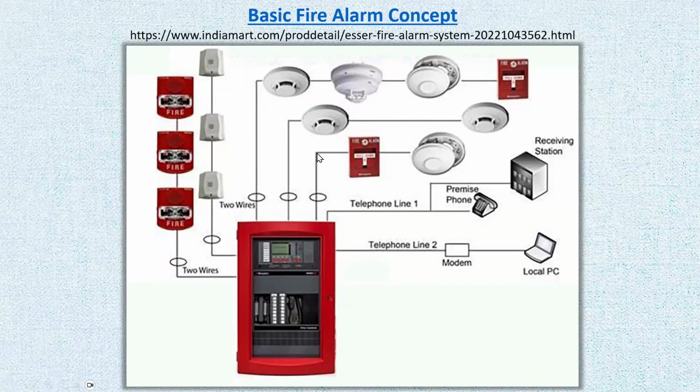Now, some of the devices can be triggered by pressing a button, like those heat detectors. They do have buttons to be pressed, like a test button. If there are smoke detectors, they can blow some smoke on it, and there's something that's called smoke in a can. It's just like a deodorant type of can. But it's called smoke in a can, and it's sold in fire alarm supply stores. So they would just blow some of that smoke onto the smoke detector and make sure that this smoke detector triggers.